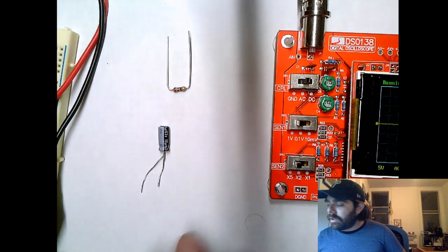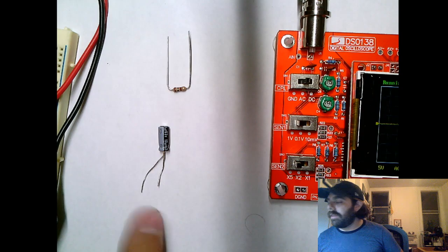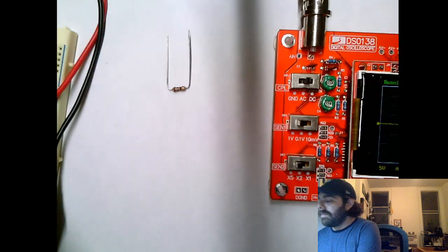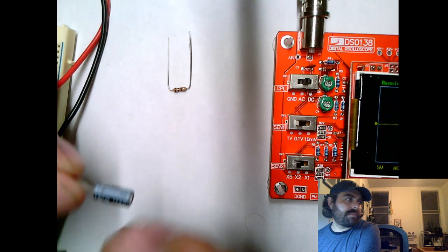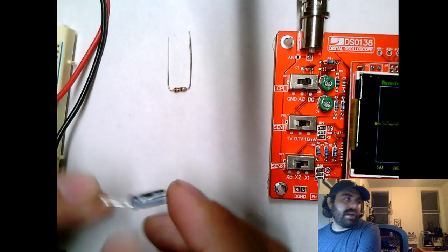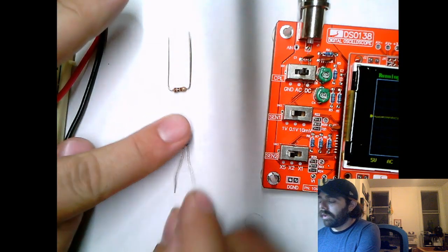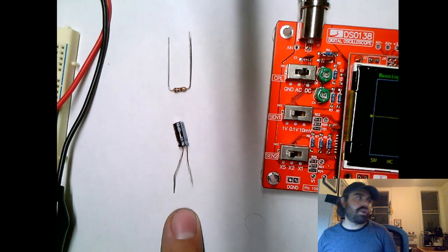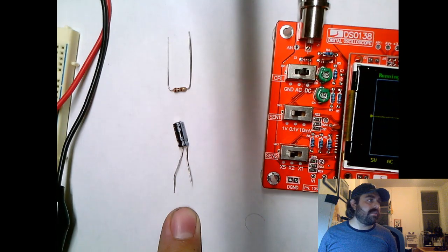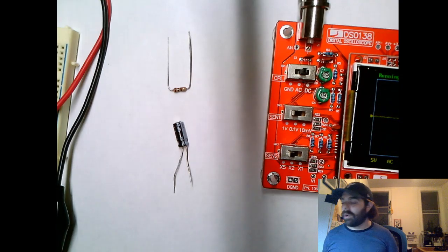This capacitor looks like a little barrel, and one leg is shorter than the other, kind of like an LED. And you might notice on the side of this is this little gray stripe with minus signs. And if you guess that that's because the short leg is the negative leg, you would have guessed correctly. Larger capacitors like this are polarized, so we have to make sure we orient them correctly in the breadboard.